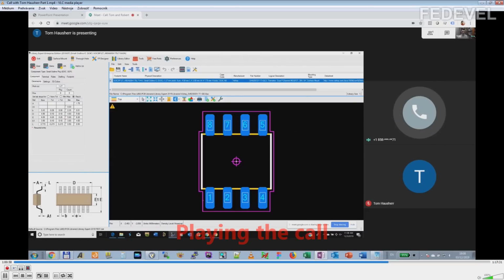Okay. If you gang mask your solder, if you gang mask your whole row of pads, and you have no solder mask in between your pads, then you might experience solder bridging. Okay. So basically, you recommend to follow the data sheets, but still be careful and check if it makes sense.